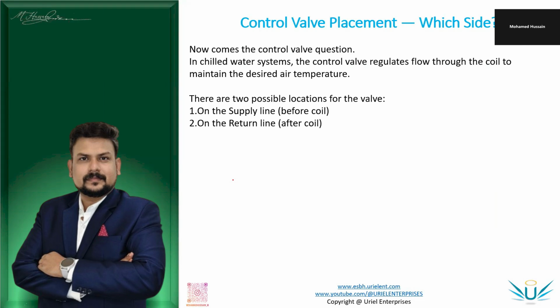When the valve is not in use, there is no flow at the coil, and when the demand is generated by the AHU system and suddenly the supply side valve opens, the coil has to fill with water. It will take some time. This is also energy waste, right?